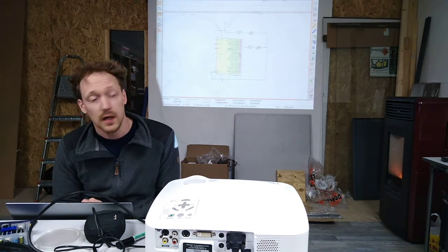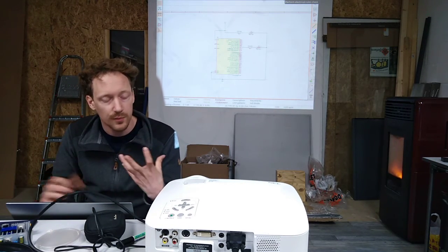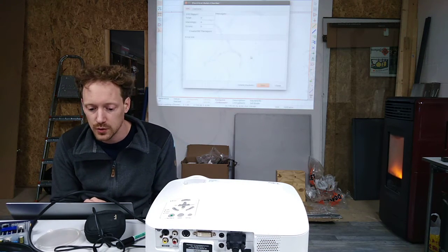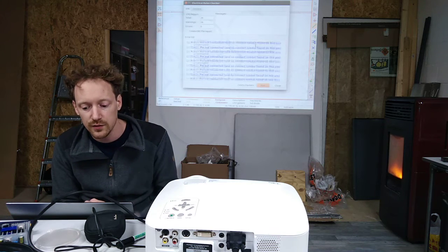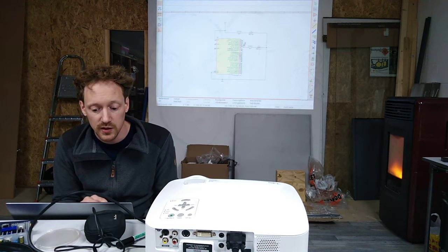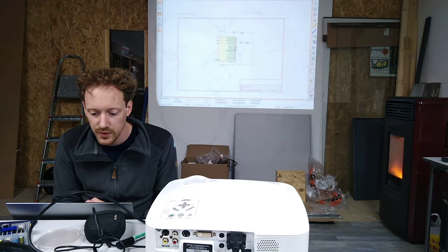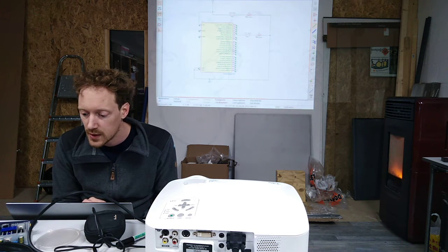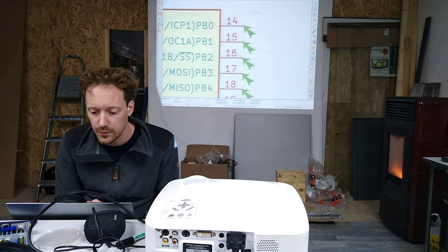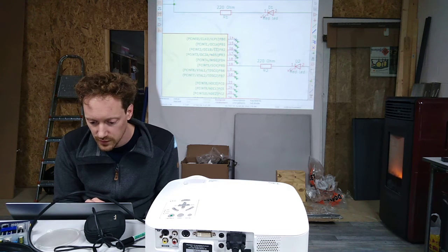Now that we have annotated and the system knows each component has a unique name, we can perform the electrical rules check. So we run it, and we now get lots of errors. It tells us that some pins have not been connected. It's very useful feedback, and it shows you with an arrow which pins haven't been connected. So we can pick the cross here and cross out all those components, and just do that for each.